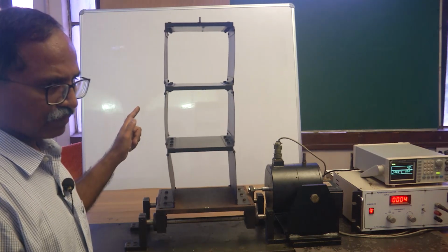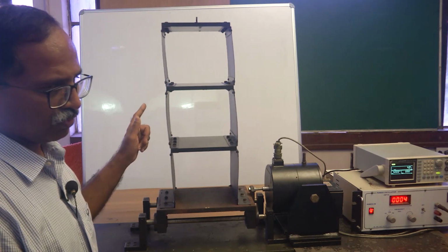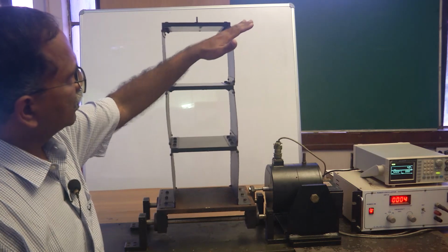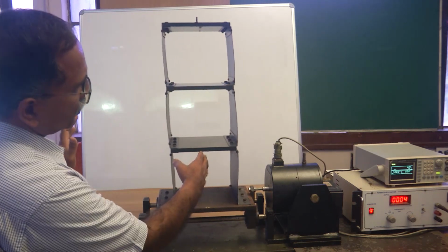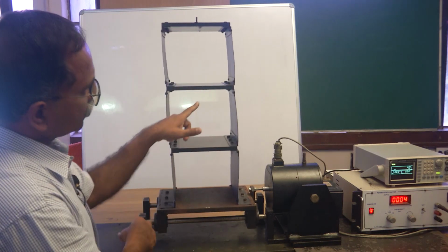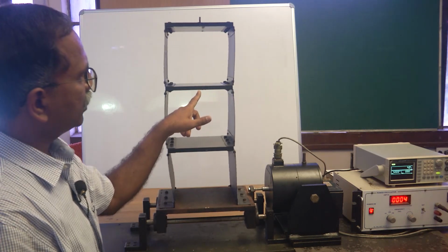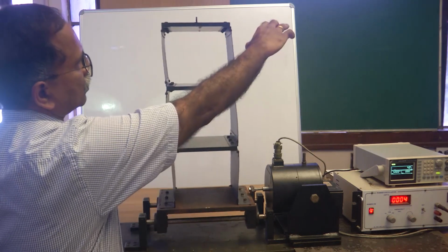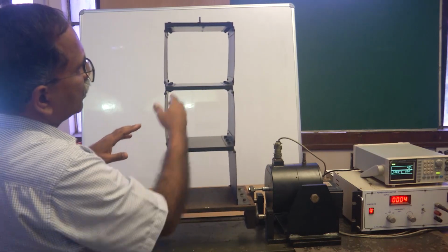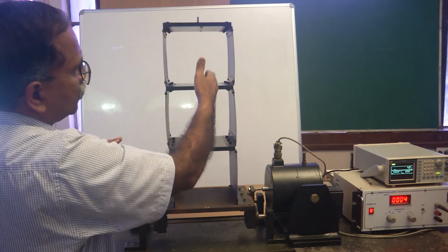Okay, so this is the second mode that we are observing. In the second mode, if you look closely, this floor moves on this side, and when it is going in this direction, the first floor goes in the opposite direction. If you watch very closely, this floor is almost having a 0 displacement, meaning that this displacement is, if it is rightward, this displacement is leftward, and if you draw the mode shape, it will have a node somewhere closer to this plate.